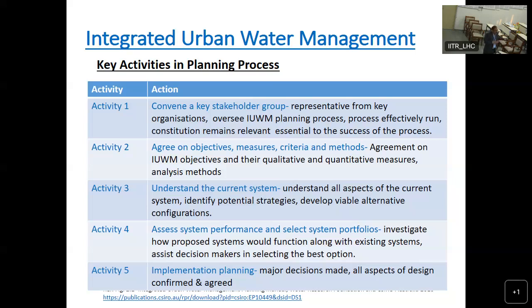Okay, we need such a large bioretention system, which will cost that much. So what is happening is some of the utilities or the water service providers, when a developer comes to them to start a new development of 500 or 600 houses, they will ask, can you show us the amount of nitrogen, phosphorus, and suspended solids? They are considering only three parameters in the case of stormwater. You will be discharging to the receiving environment.